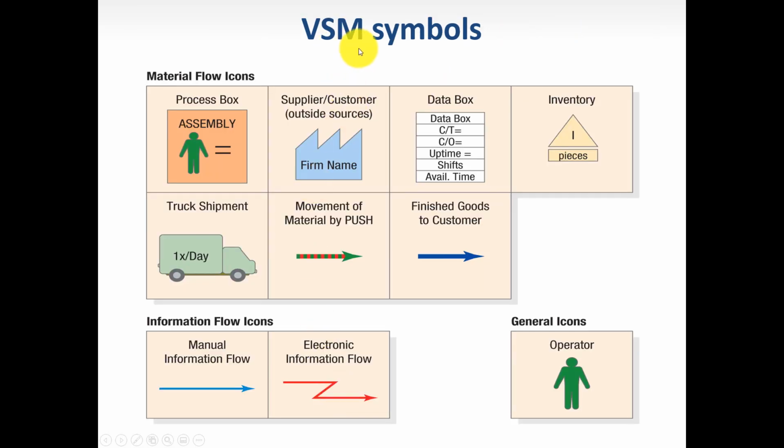Okay, so the value stream map uses a lot of symbols like the ones you get to see here, sometimes trucks, even planes, arrows. They have some particularities because you have arrows that express movement of materials, but you also have arrows that express information flows, even as hard copies like orders or even electronically. You also indicate the number of operators that a specific workstation might need. Here, you remember that? That's the inventory triangle. It is also used here.